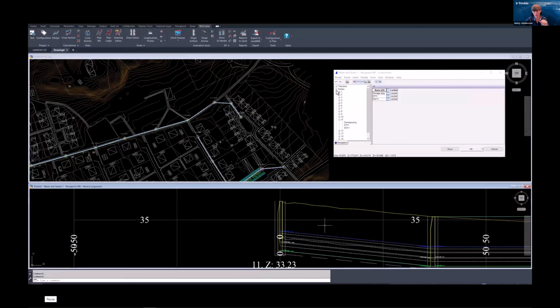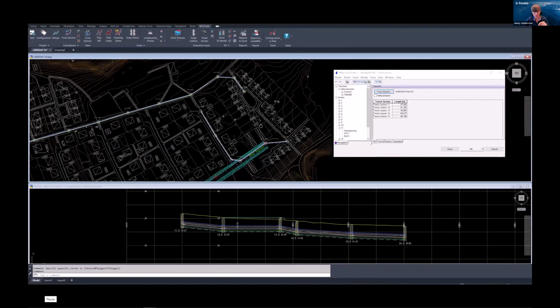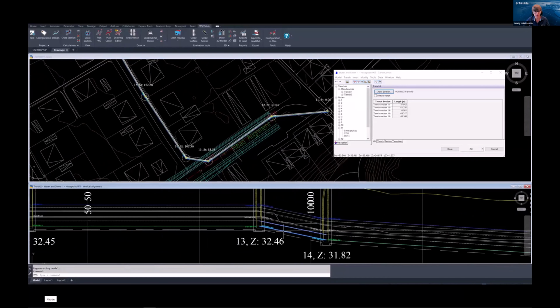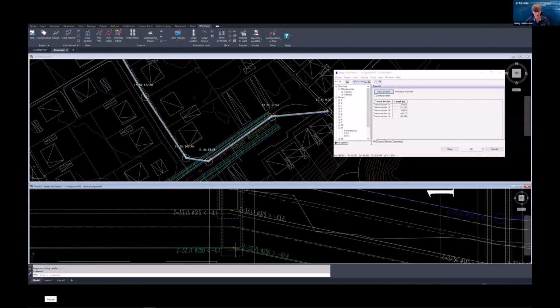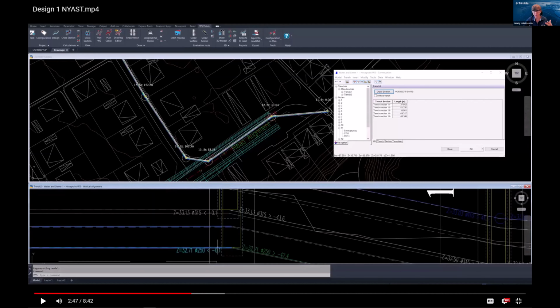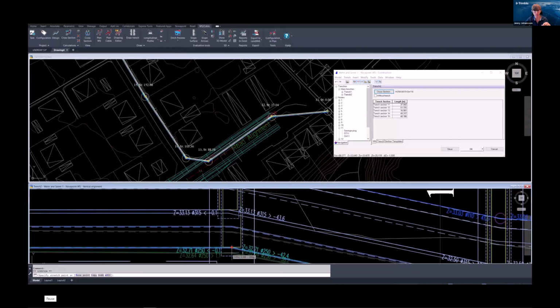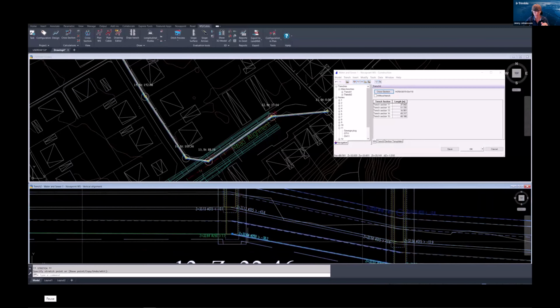From here, we will go over to the vertical drawing once again, and we're going to look a little bit closer into the set values for the designed trench. And as we can see here in node 13, we have manholes, they are yellowed, and you can always change a set value for a manhole just by right-clicking it and giving a new set value, but you can also click with left button on the mouse and then grab the grip that shows. And when you drag this manhole down, the pipes will follow.